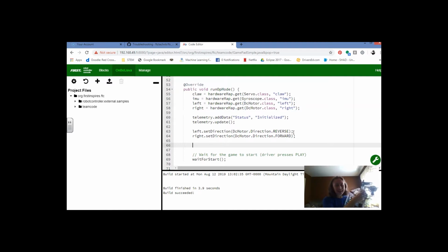So I'm just going to make a guess and then make sure I really watch my robot carefully when it sets up, and if the arm goes in the wrong direction, I'll stop the code, program it to the correct setting, and then rerun it. So I'm just going to take a guess that this is 0, and halfway, that's always going to be 0.5. So let's start off with the servo, which is named claw dot setPosition, and we'll set the position to be 0.0.